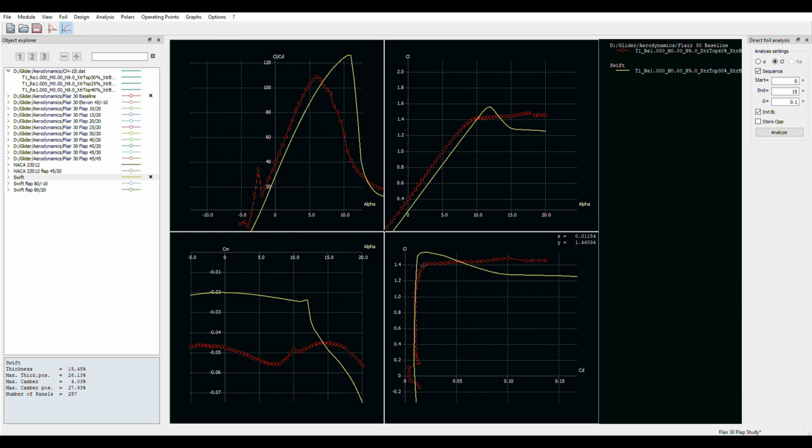And it does it extremely well, and it gets up to the corner here, and then you lose that effect rather quickly, and that's kind of mirrored by the sharp stall that's here. And then the drag goes up rapidly, drops off. The Flair does have the advantage that you can continue to try to pull more CL. You get a little bit more CL, and you just get a boatload more drag. And the Swift, you drop off.